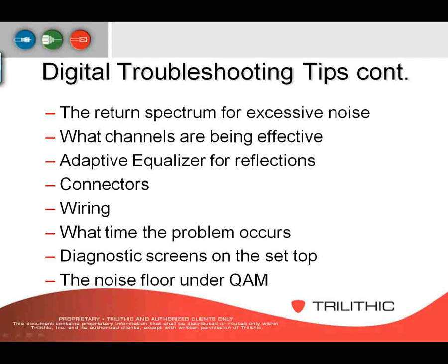Because different problems, especially when you're talking about ingress and noise, can happen more at night or more during the day. Maybe it's a particular machine shop in the neighborhood, and whenever they turn on a particular drill press, that's when they start causing bit errors or having problems on the customer's set when they turn on that piece of equipment.